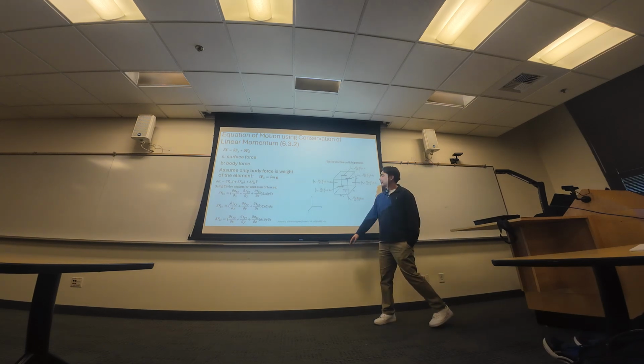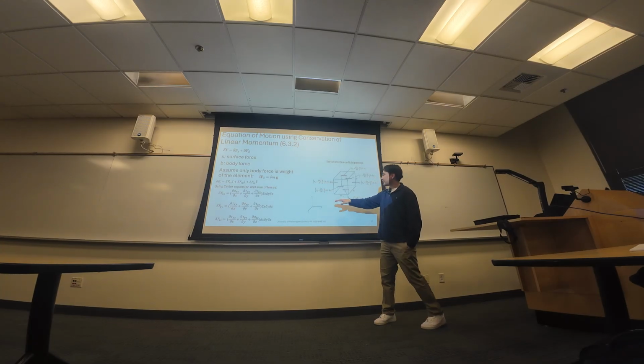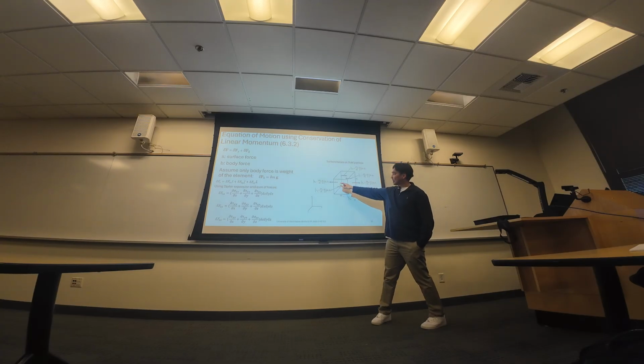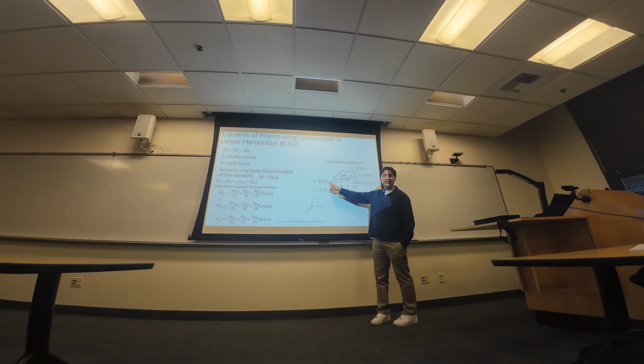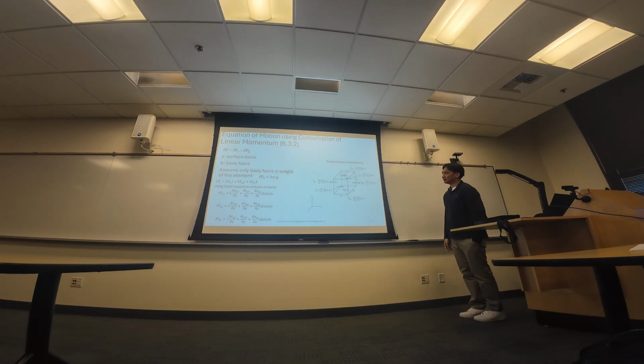Okay, I'll just go through one of these. So sigma xx is your stress, right? If you add the change of your stress with respect to the x direction, and you multiply by delta x over 2, because we're always from the center, this delta y and delta z is just the area you applied it in. And that's how you get it, right, stress times area is force. So these are just all forces.